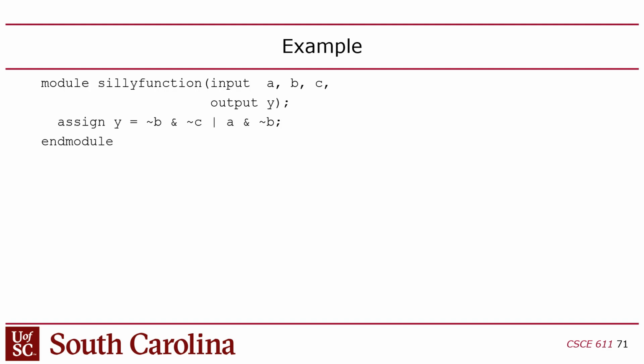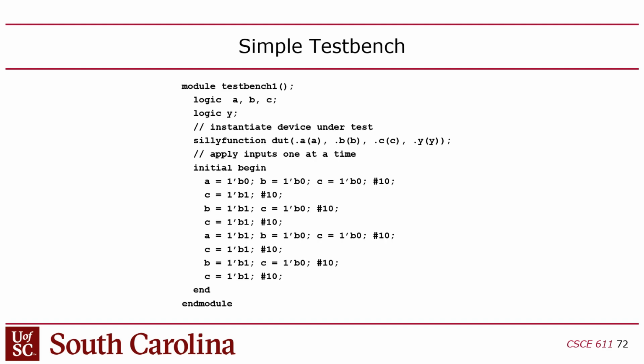But keep this in mind, though. The test bench is not synthesizable. So only this is synthesizable, meaning anything you design that you want to put in hardware is going to have inputs and outputs. The test bench doesn't have inputs and outputs, but it's not something that's going to go into hardware. It's only for simulation purposes, right? So here's a test bench. Notice that there's no inputs or outputs there. It just says module test bench. It's kind of self-contained. And then you simulate this as the top level design in the simulator.